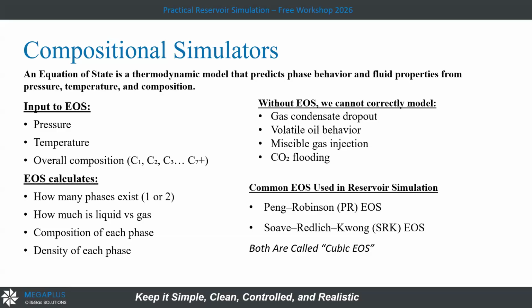As an example, in enhanced oil recovery, of course, it's simply a kind of tertiary recovery that we use after improved oil recovery or the secondary recovery. If we have some unmovable oil, we will start water injection so we can sweep the oil until we reach the irreducible or residual oil saturation. To get this residual oil saturation, we will change the physics of the fluid.